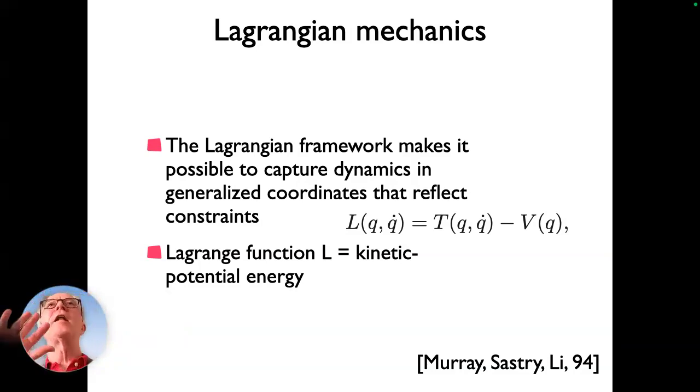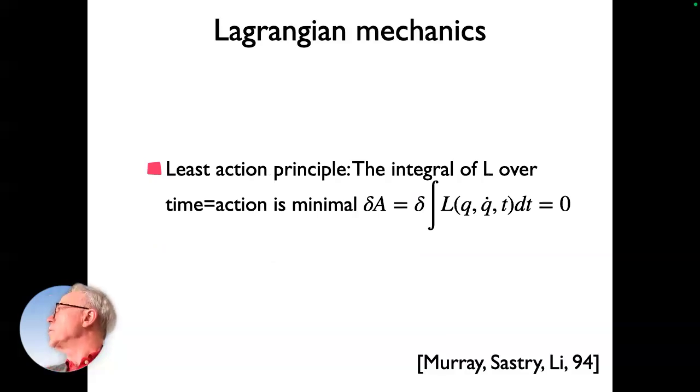This is still without any actuators, right? This is the conservative closed system, so there's no energy in, no energy out. It's just the arm with no friction, flopping around in gravity. So the integral over time of that is called the action, and it's one of the physical insights that the realized trajectories by any system like that are the trajectories where that integral is minimal.